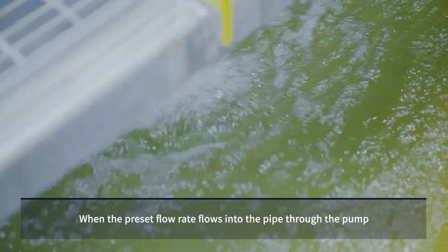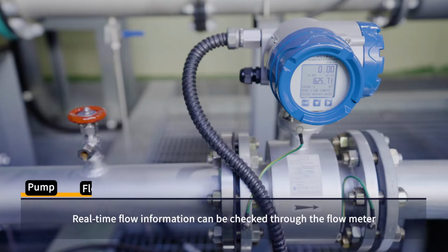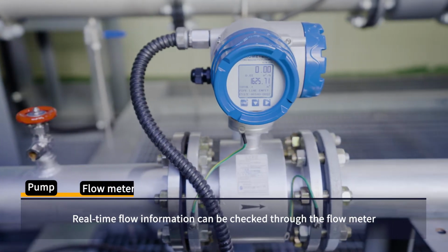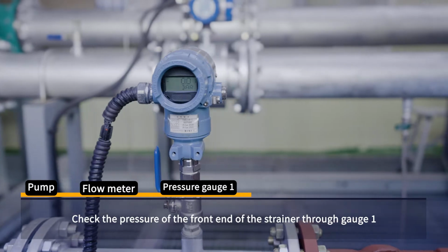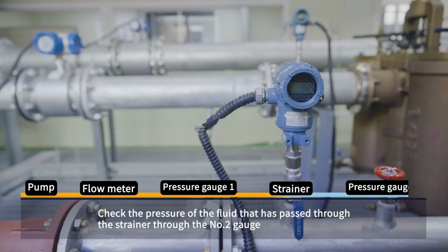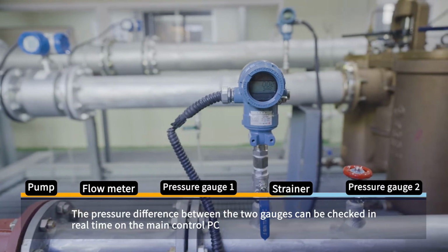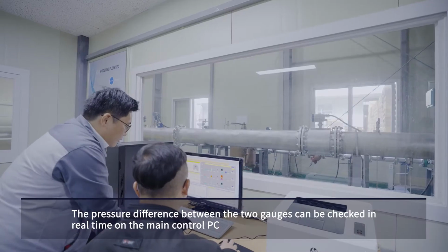When the preset flow rate flows into the pipe through the pump, real-time flow information can be checked through the flow meter. Check the pressure of the front end of the strainer through gauge 1. Check the pressure of the fluid that has passed through the strainer through gauge 2. The pressure difference between the two gauges can be checked in real time on the main control PC.